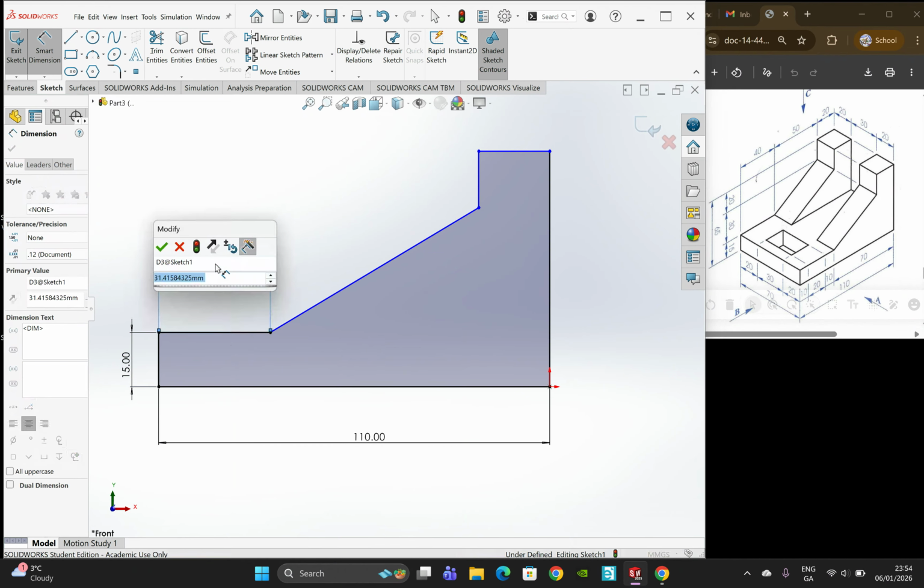So the most appropriate face to actually select is this one here at the back. So if you click the back face and click sketch, the easiest way to do this now is up here you have a little tool called a display style. If you click this and go down to the fourth option down, it'll show you the hidden detail line, because technically we're looking at it from the back now. You can see we're looking at the back of it. So press your space bar if you rotate it, and there's an option there, as I said, hidden detail.